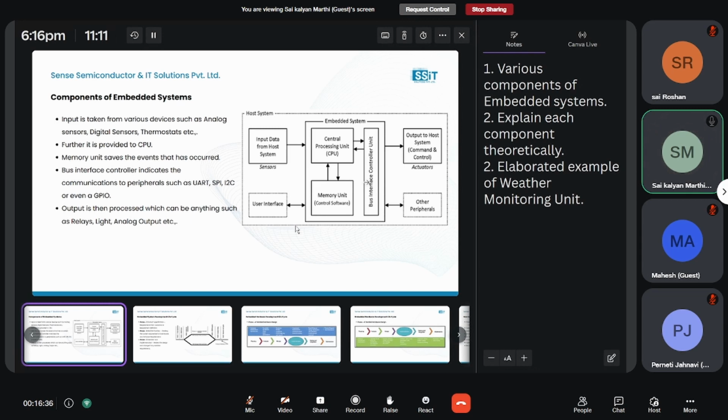See, basically, a controller will have only a part where it can process and send the data outside. But it can have peripherals like UART, I2C, and SPI, but it cannot contain all the components which are required for high level peripherals such as Ethernet or Wi-Fi. So for that, we need some external controller, which we need to communicate with using some other advanced peripherals like MDIO, MDC. You will come across these while working in industrial internships, or if you start working in an industrial company. Then you will get to know what these different chips are that are available.